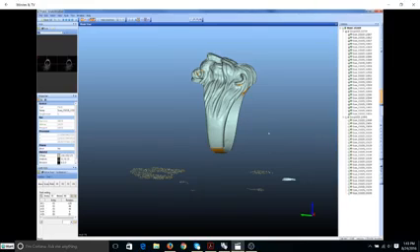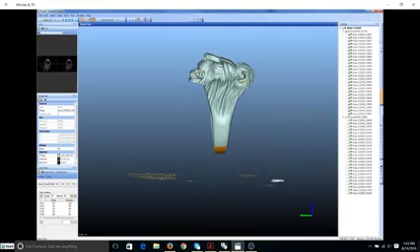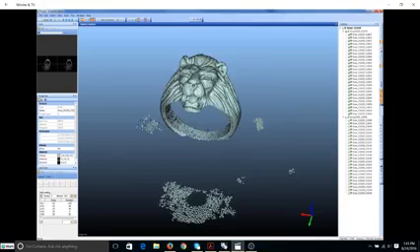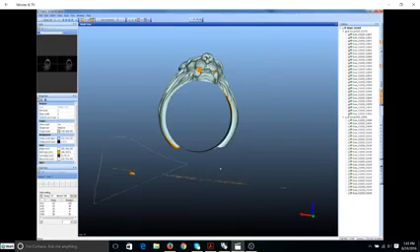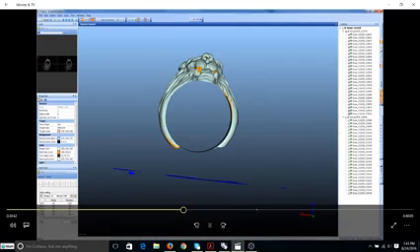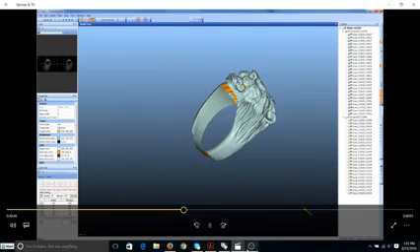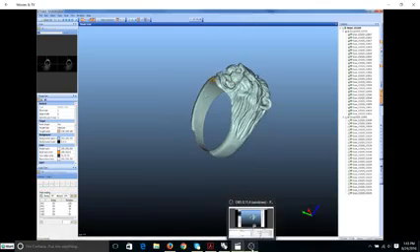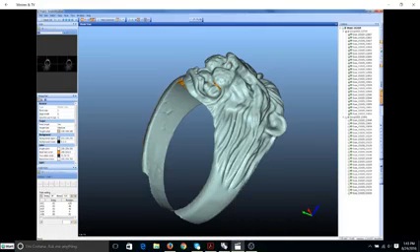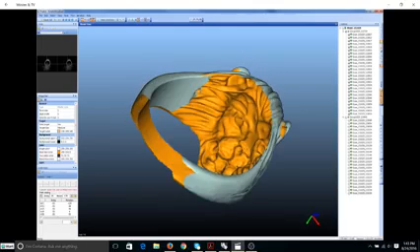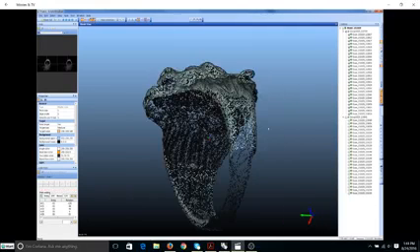So I turned off one of these, and now I'm going to go into the edit tool here and capture some of these polys. So notice that this is part of the table that's been captured. I'm going to go in here, and I'm going to grab that, and it turns blue, and I'm just going to delete it. Just the lasso tool. Right, it's just a lasso tool, and now I also bring this into the center of the viewport. If this was off to the side a little bit, for instance, I would know that I have some data I have to look for and get rid of.